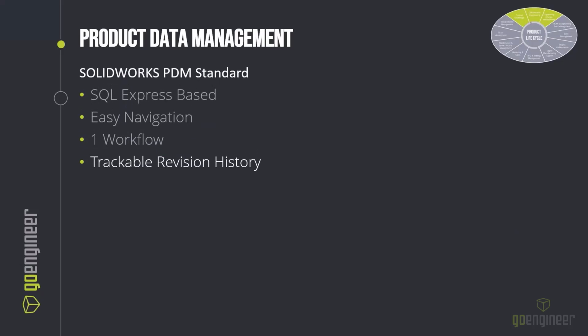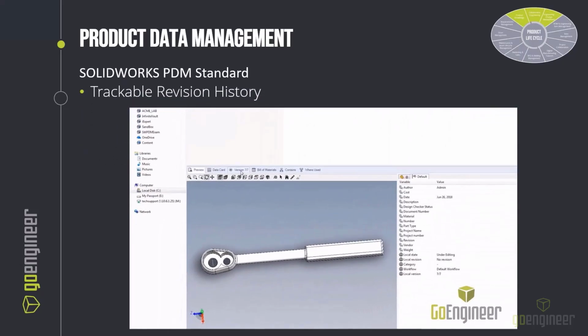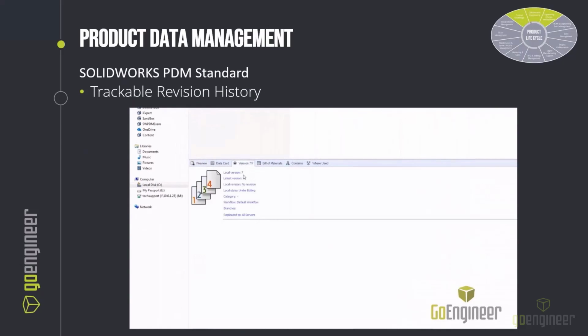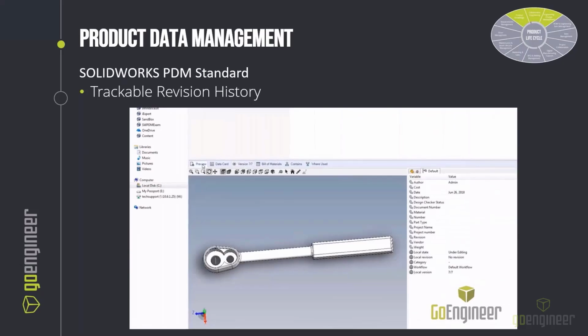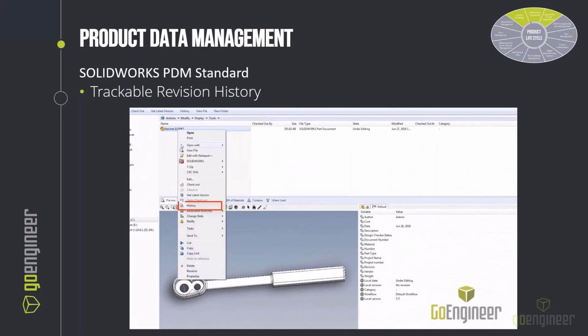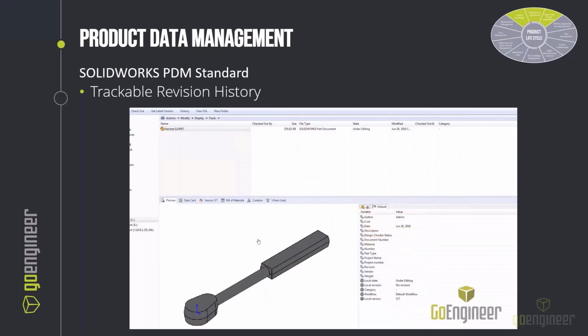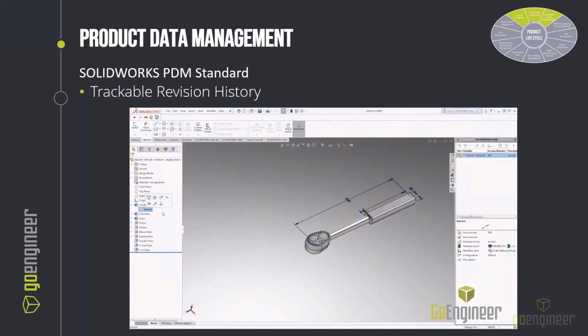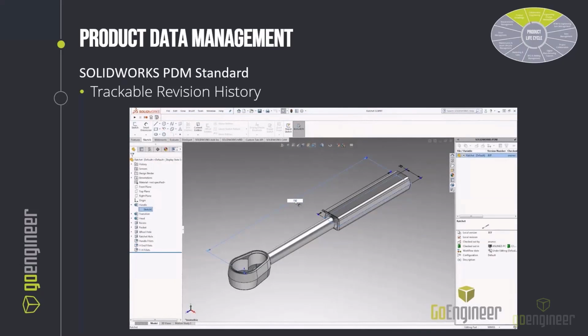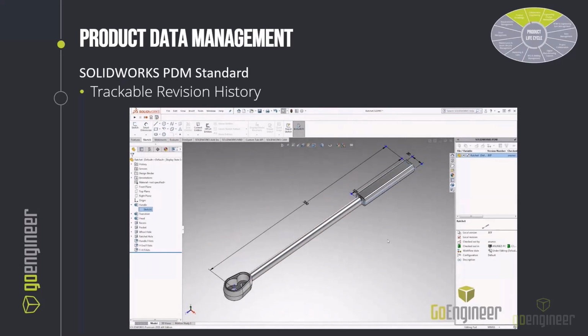And as data is processed more efficiently, users need to be able to see the history of files. With SOLIDWORKS PDM, you can manage and modify files and retain a history of all the file changes. This allows users to retrieve older versions of files through the history dialog window, where you can roll back to earlier versions. Users can "get" selected versions to be used as the active version and use those in their designs. New versions are automatically created each time a file is modified and checked into the vault.